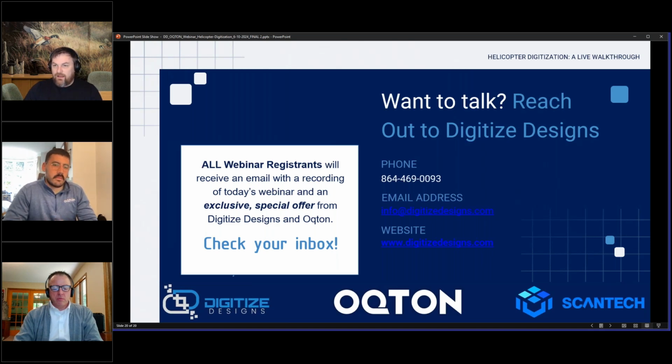And then the other one is we try to save in a neutral format that is more relative to where we're going. So if I'm going to NX, I save it out as a Parasolid neutral file, instead of using an IGES, which is your lowest common denominator, or STEP, which are pretty good, right? Sometimes I see benefits in saving to Parasolids, or an SAT for the ACIS kernel softwares like CATIA. So if you save out those, sometimes you get a little bit better translation from one to another. And then those softwares are able to open them because you're throwing it in their native container.